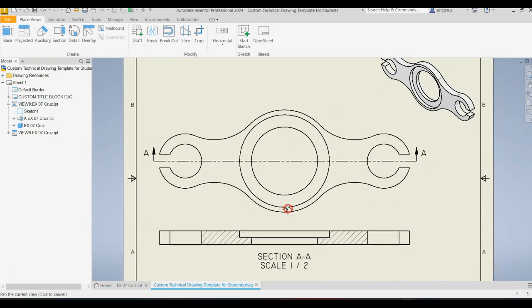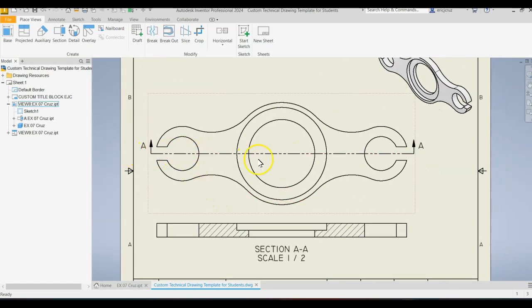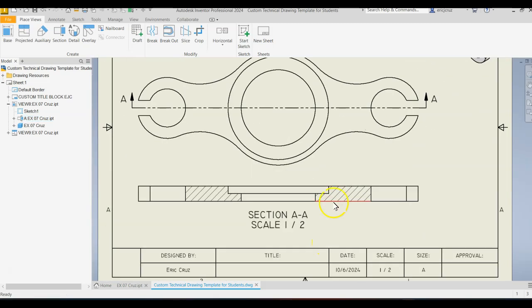And now what we're seeing is an imaginary cut line go through this part. That imaginary cut line then shows us the part that was cut. So these are section lines. So you can see how it's touching right here. There's a hole here. So the imaginary line's not touching that, but it cut through here. You know, like for example with the laser cutter or something. So these lines represent those cuts. That is one way we can see more detail within a part to make it easier to dimension.